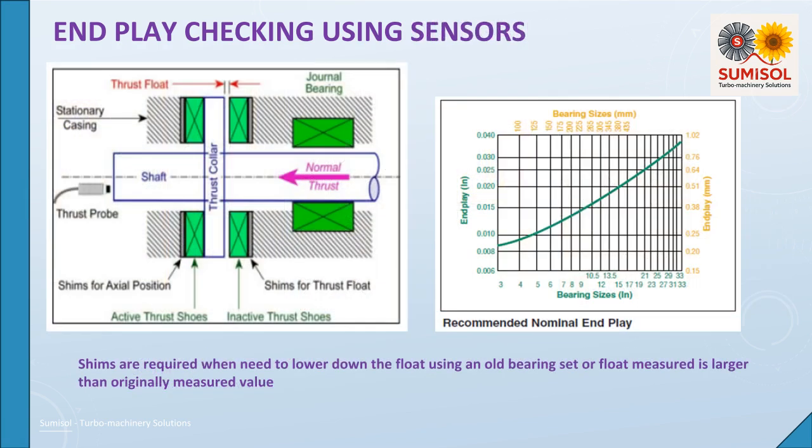Mount the proximity probes so their axis is parallel to the shaft axis. Position the tip of each probe at a specific distance from the target surface, typically around 0.050 inches, depending on the probe's linear range. This distance is adjusted to achieve a specific gap voltage, e.g., -10 VDC, in the linear range of the probe driver. If the shaft end is countersunk, the probe should be mounted off-center, ensuring the tip is at least 1.5 times its diameter away from the edge.